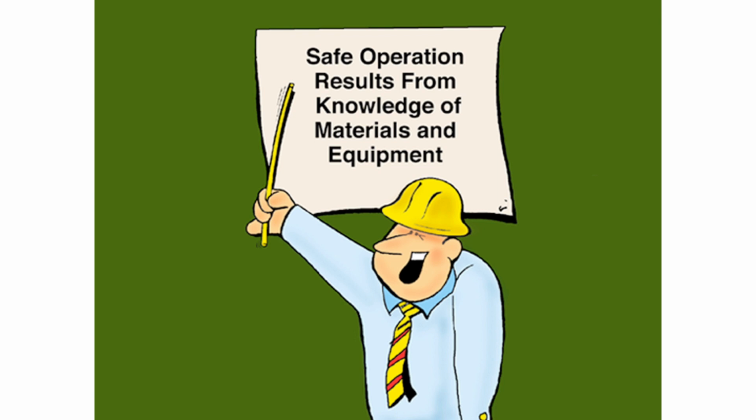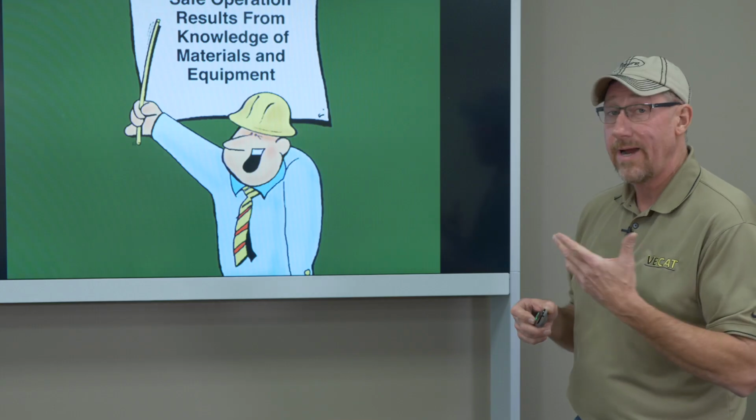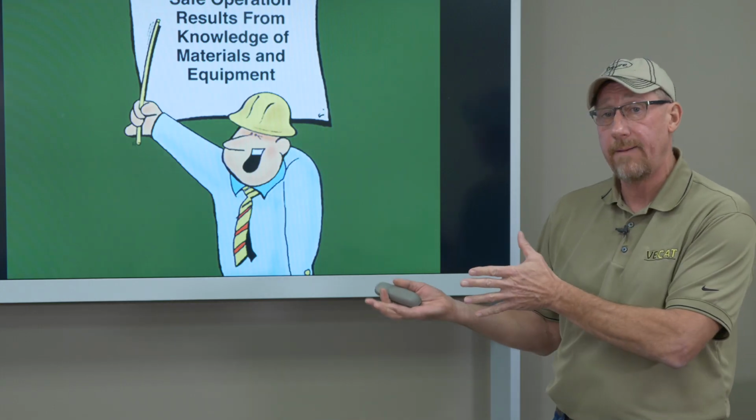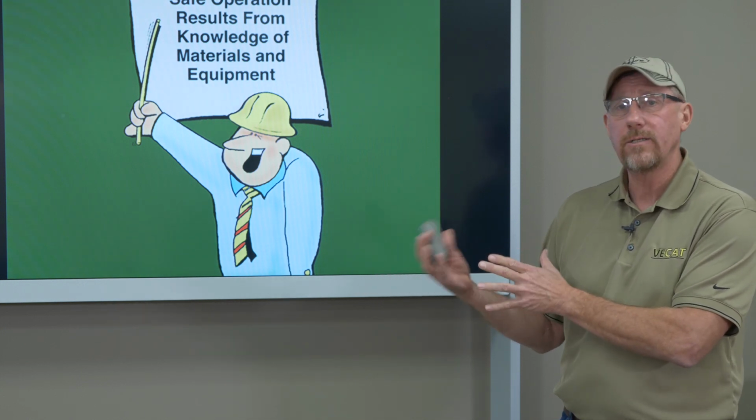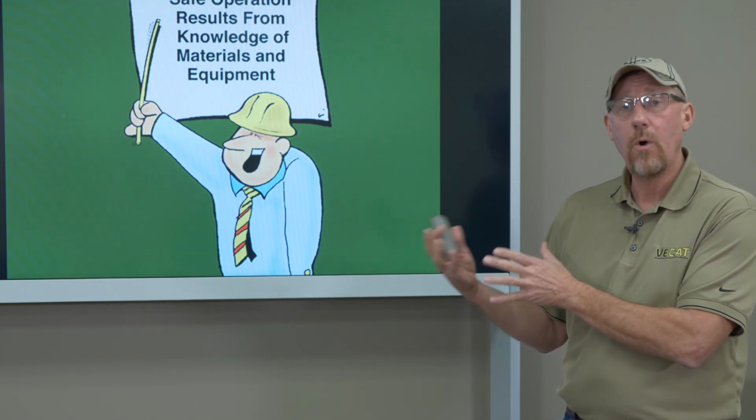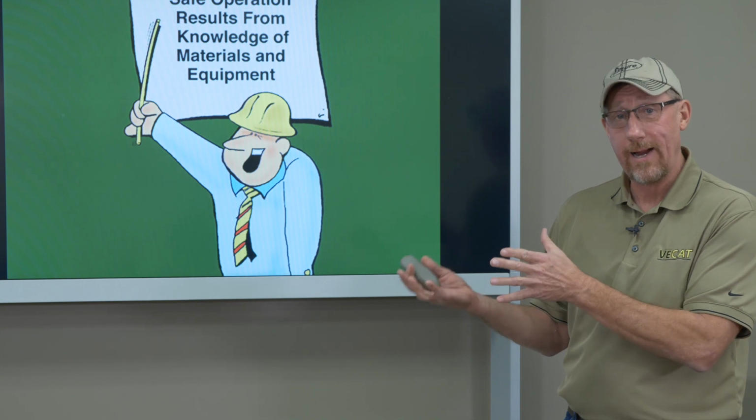So the safe operation of equipment and the materials we talked about, the two go hand in hand. Don't try to short yourself when you're using a distributor truck, especially with hot products in it. We don't want anybody to get burnt. The scariest thing for me is to pull up onto a job site. Somebody's got the burners lit, we're warming the oil up, and I ask them, what are we shooting? And they have no idea what product's in that tank or how to handle it.